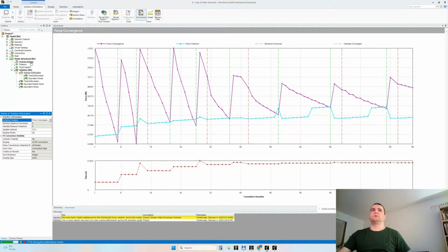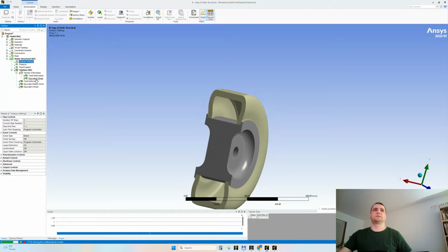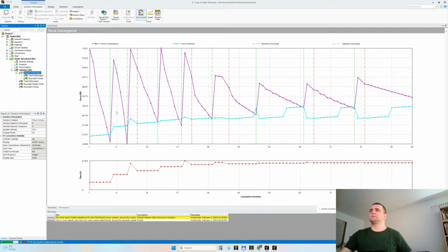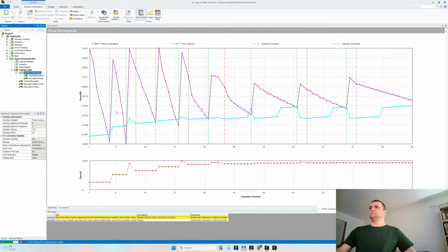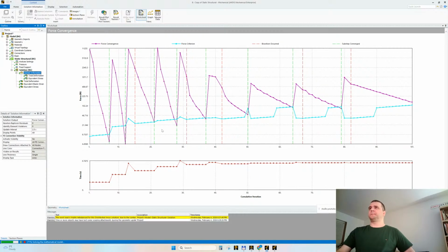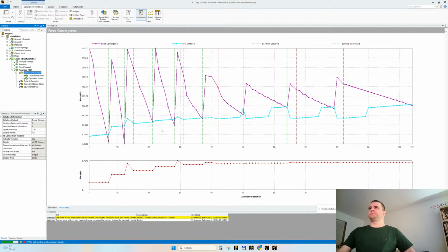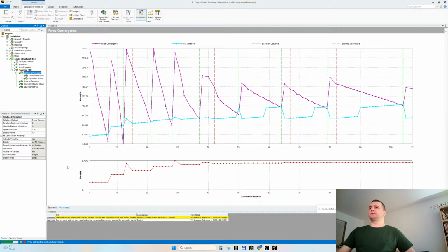I should be more generous here, not to leave it program controlled, but applying some values for manual time stepping, let's say. Come on. Yes, it works.